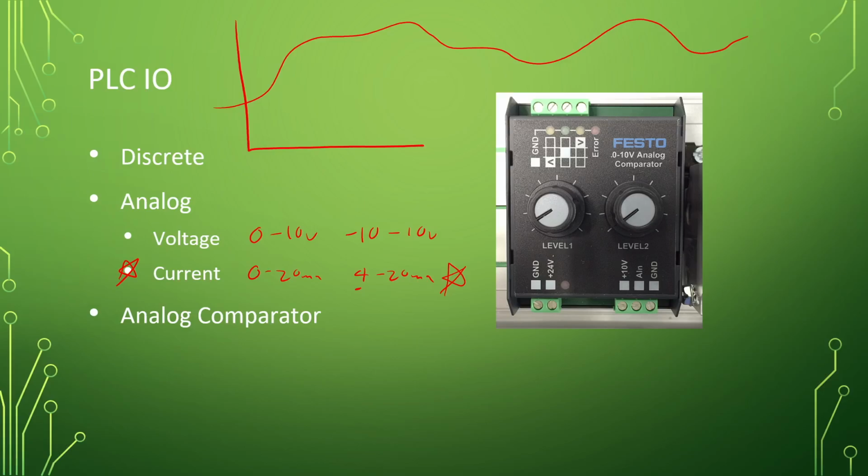All this is a voltage measurement with a high precision resistor. Inside your device, you're going to have a resistor that you know the value of. If you're in 110, hopefully, you've seen a resistor that's 100K plus or minus 5%. That isn't going to cut it here. You need to know that it is 5K or 5 ohms or whatever the magic number is.